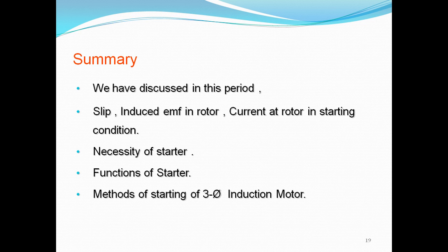When the motor reaches 70 to 80% of its normal speed, all the starters in it will be disconnected and rated voltage is applied.